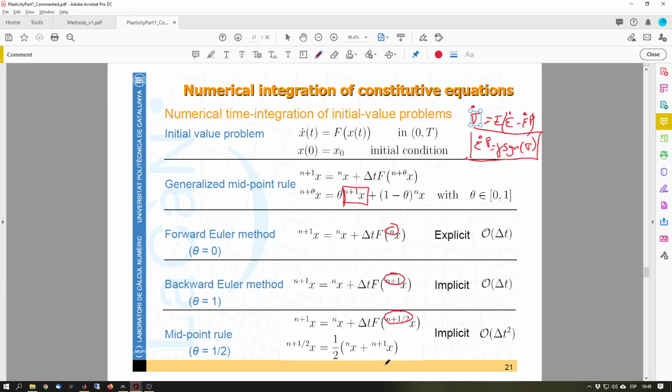The one we are going to adopt, in fact, is this one, the backward Euler. We know this is forward Euler; we've seen that in dynamics. It is conditionally stable, so we may have instabilities, and we don't want to mix numerical instabilities with any instabilities we may have. Plasticity problems may yield unstable results, but they are physically unstable. When regions of our domain plastify, we may have collapse, which means an instability, and we don't want to mix numerical instability with the physical instabilities.